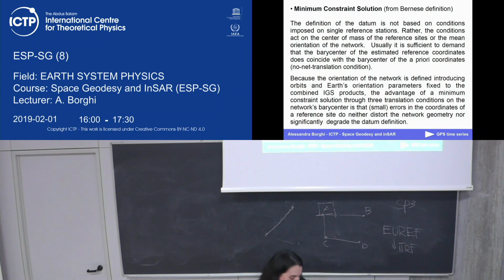But if you use a network or reference frame, you are going to use this network constraint as a rigid body, and you are going to check how this rigid body fits with the theoretical values. So in this case, if you have this antenna covered by 2 meters of snow, you can say, okay, for this day I remove this reference station, because when I check the residual of this adjustment between the observations that we obtain and the theoretical values, I found a very high residual value.